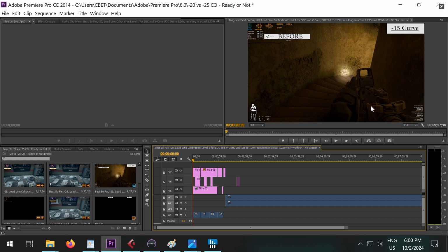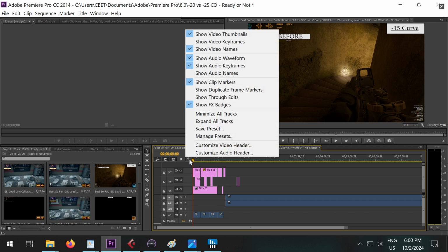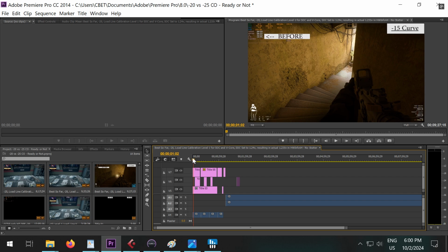The default level for the CPU load line is 2, and for the SOC on ASRock is 3. So CPU level 2, SOC level 3. And what you'll see in the video, it works just fine on 15. 15 is like a small Curve Optimizer value. Pretty much 90%, 92% of 7950X3Ds can do minus 15. So that's why all these YouTubers are like, oh, just set it minus 15, it's all good. What they don't talk about is the fact that you gotta have load line levels correct, or even that will crap out. Not necessarily right away, but check it out.